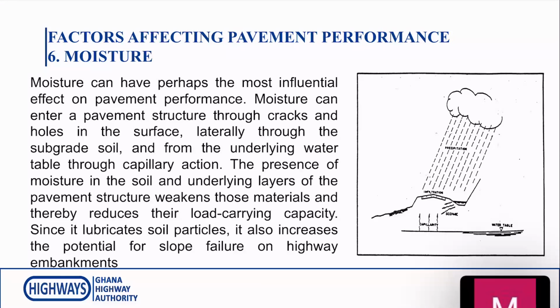Water on the pavement can create problems for the bituminous layers. If water enters an asphalt concrete structure or surface dress structure, it causes what we call stripping. That is the removal of the stones from the bitumen, which will lead to cracks and potholes. So moisture is very, very important and has to be considered when one is designing road pavement structures.